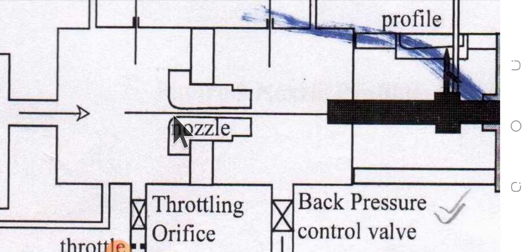So as we are moving the probe, the pressure is decreasing, which means the velocity is increasing. The pressure is inversely proportional to velocity. What does a nozzle do? It converts pressure into velocity. So definitely here the pressure will decrease and the velocity will increase.